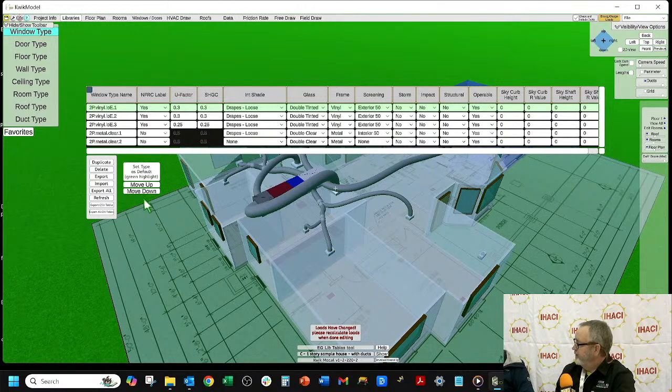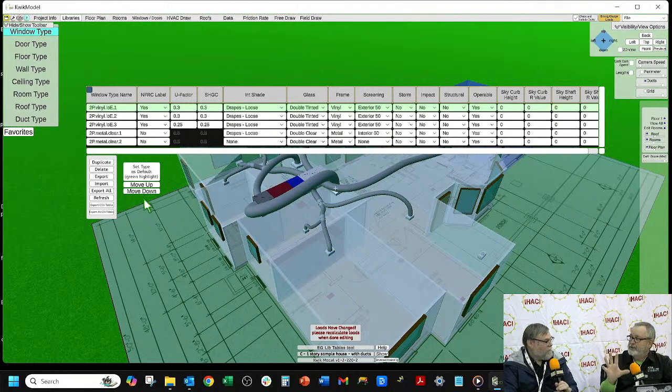One question I get asked all the time, what usually is your biggest bang for your buck? Is it insulation? Is it windows? Or does it depend? It depends on the age of the house, but for new construction, windows is probably the first thing you should focus on. Invest in good windows. Have an architect design the house to not oversize the windows. You can get the same effect from a smaller window as you can from a giant window. So architects have learned to optimize light opportunities.